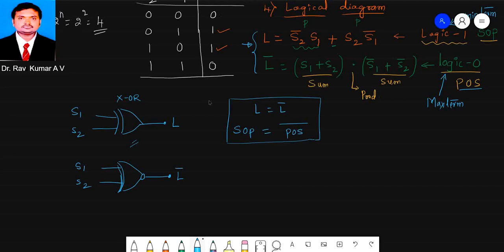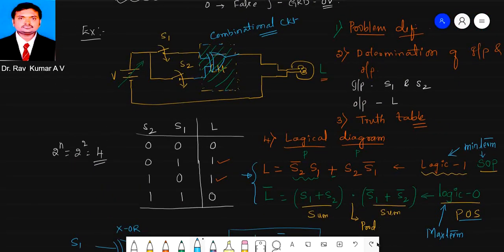Now we'll come to what a combinational logic circuit is. What are combinational circuits? See, once you give the input, automatically your output changes. Is any memory required here? No. No memory is required to store your data. There is no memory here. So I can say directly that a combinational circuit is a circuit in which your output responds directly to the input changes. Here no storage elements are involved, like a memory. This is called a combinational logic circuit.